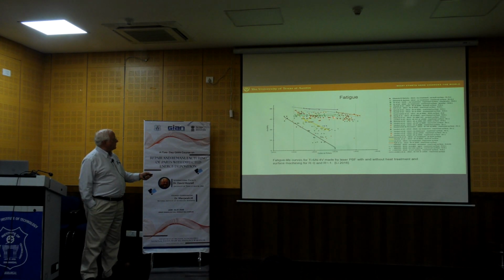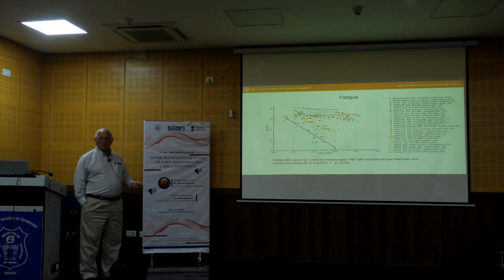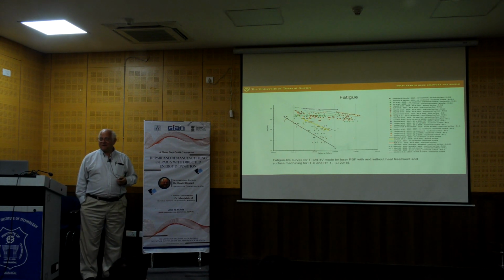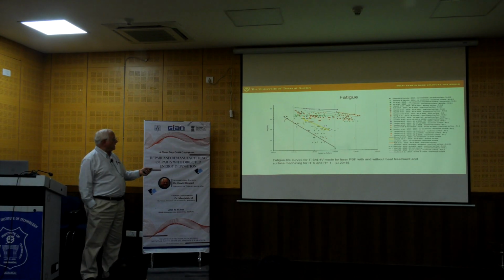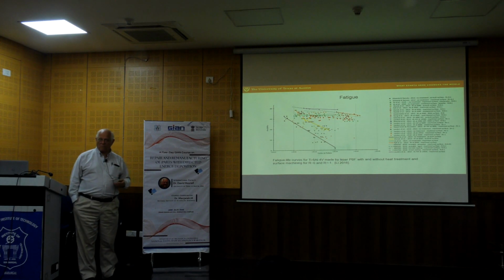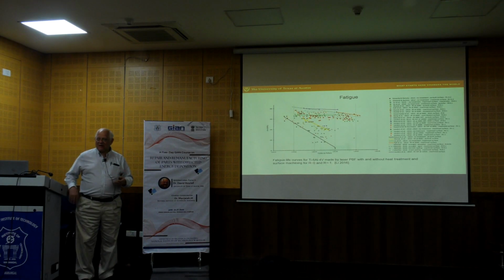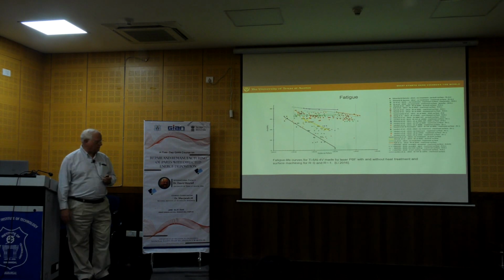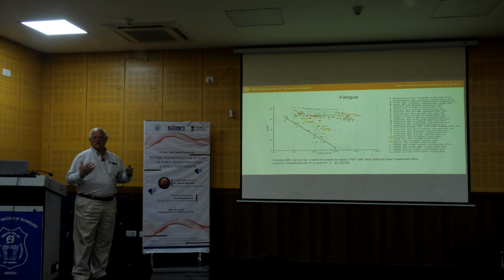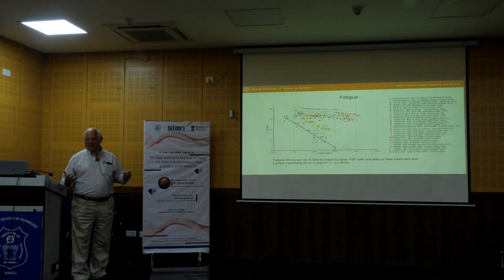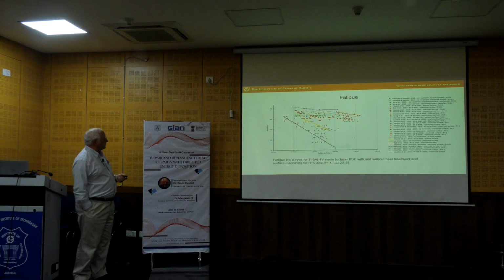And you can see there are quite a few results up here that are sort of banging on the door of the raw material. A number of investigators have been able to produce parts that have outstanding fatigue properties, even coming out of an additive manufacturing machine. And again, some of these were heat treated, some were hot isostatic pressed, which typically will restore all the properties.